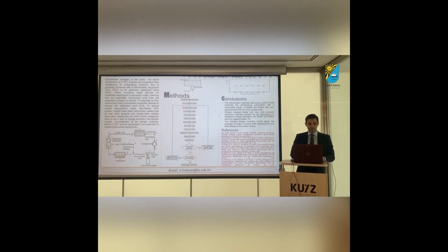In this work, we basically want to utilize the energy loss or heat loss in the expander in the AC system. Here we notice that there is a tremendous amount of heat loss in the expansion, so we try to harvest that heat and convert it into electric power. Eventually we can increase the overall efficiency of the system.